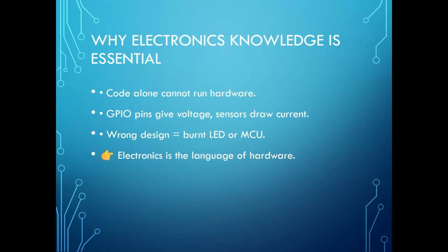Why is electronics knowledge essential? Let me ask: can programming alone light an LED? Any thought? No. You need to know how much current it needs, how much voltage it can handle, and how to protect it.